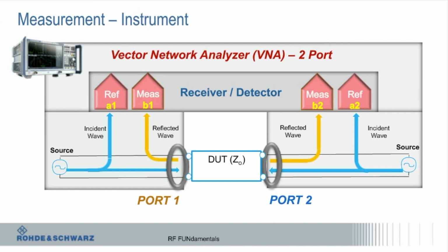So this is a 2-port VNA, and it looks like there are 4 connections. There are really only 2. One is the return path or ground, depending on who you're talking to, but it's ground, all said and done. But we make ones with more ports. So 2, 4, and we have one I'm doing with a customer that's 24 ports. Each port has 2 receivers, and they share a source. So pretty cool.